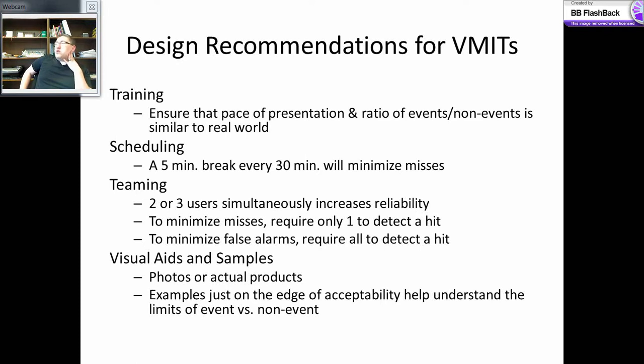So what do they do? Well, they don't rely on just one sensor because no matter how reliable a sensor is, some will fail some of the time. And so they have multiple sensors. Maybe they have 5 sensors or 10 sensors on the front of the vehicle. And they have a set of rules in place. They sort of have a team of sensors. Now, they don't all have to go off at the same time, but we also don't say just one. Because if you had 10 sensors and any one of them could set off the airbag, what are the chances that at least one of them is going to fail during the life of the vehicle? It's probably a decent chance.